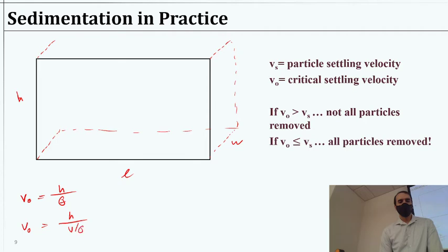And if we take that volume term we recognize that's going to be length times width times height, right? Or in the case of a circular one, we take pi r squared. Okay, so this height then, we can rewrite this and say that's the height divided by height times width times length divided by Q. And we notice that our heights are going to cancel and that Q term can come to the top.